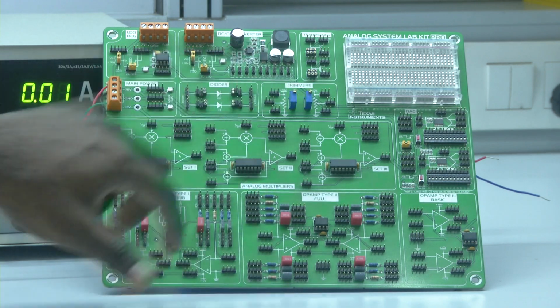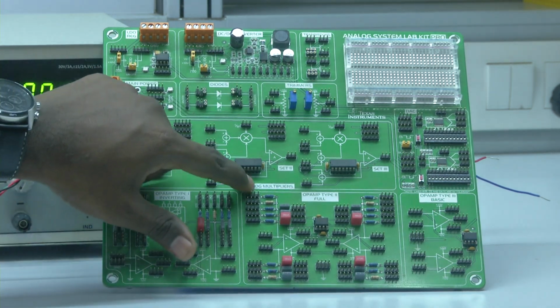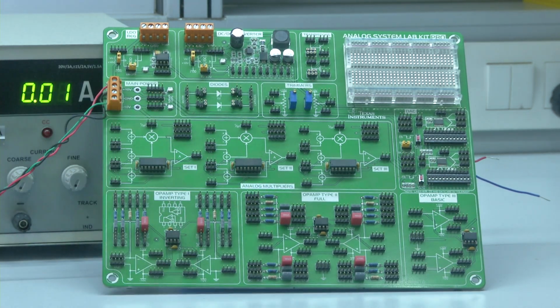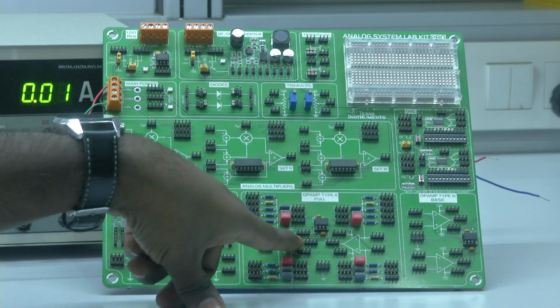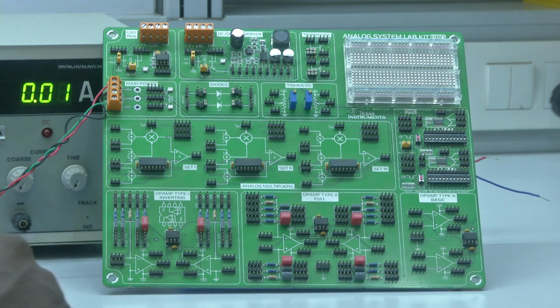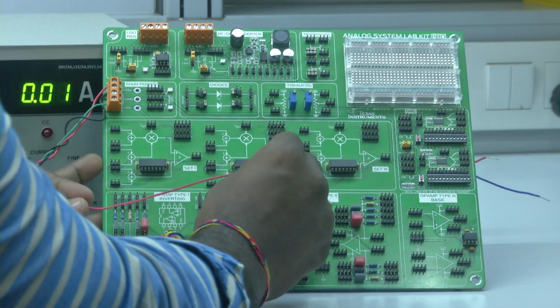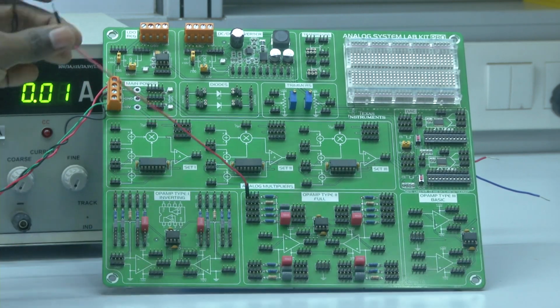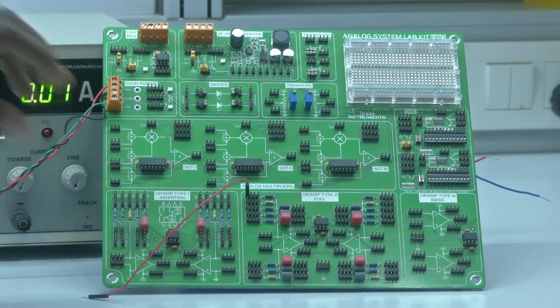The other end of the resistance, if you notice, is connected to the banana connectors. Similarly, on the output side, it has provided a banana connector. Since the input has to be connected to the R1 resistance, I will take a jumper, and the input resistance should be 1K. I will provide the input at this terminal.